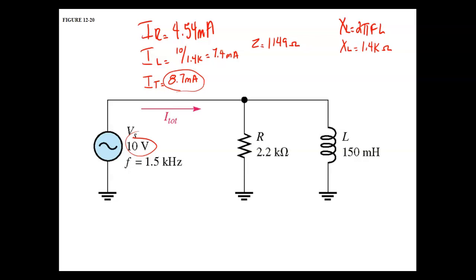If you had 3 ammeters and you showed that to the people in DC, that would freak them out. Miss Bush told us the sum of the currents have to equal the total. What else? Can we do the phase angle? Yes. Reactive current over resistive current, right?